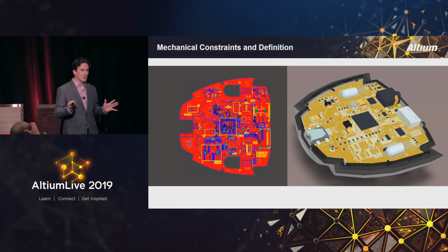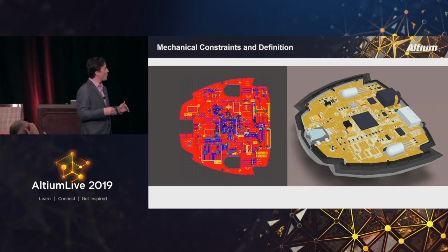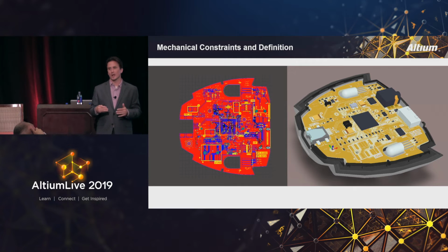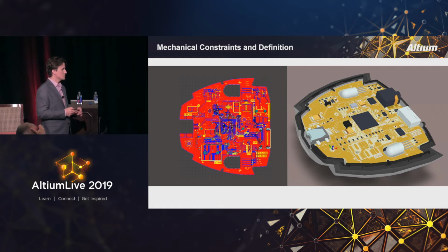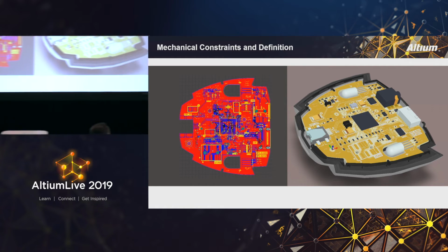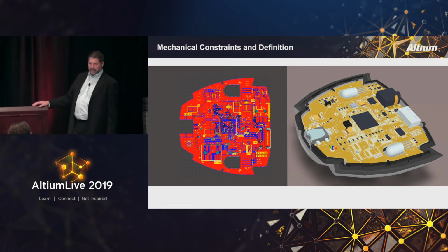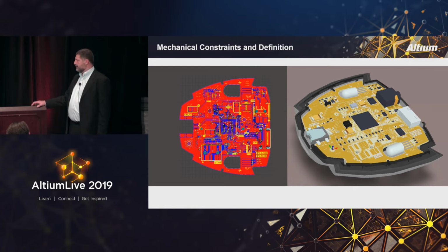I've dealt with it, and if at all possible, have all of your connectors come off of one side of the board. Yeah, the inductive loop's going to be much shorter that way. If they're on the same edge of the board, it's going to be a fraction of what the inductive loop would be if they're across the board.